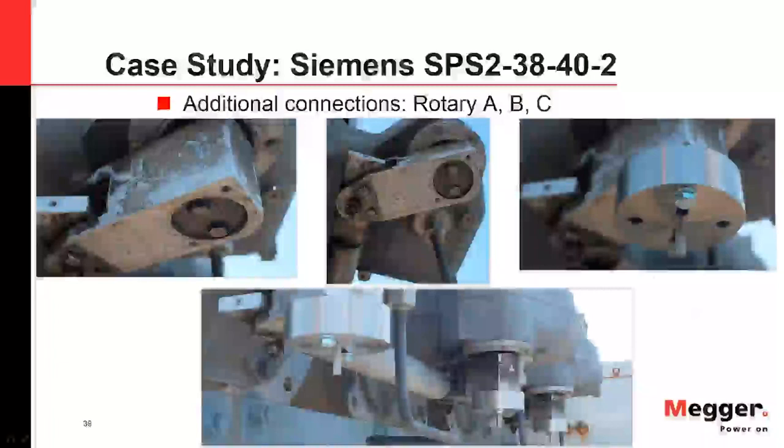And then additionally, even though the manufacturer recommends linear ones, we're going to hook up some rotary ones. So you have one hooked up to A, B, and C phase. You'll see I took off the housing, and underneath there's the spline. So as that linkage rod drives in and out, it rotates the spline, which goes from linear movement to rotary movement, and then that rotary movement is converted back to linear movement inside the tank housing and drives the interrupter back and forth.